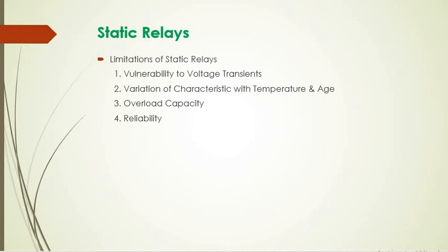Next limitation or disadvantage for static relays is overload capacity. The static relays have lower short-time overload capacity compared with electromagnetic relays. However, with improvement in semiconductor technology, there is significant rise in thermal overload capacity of static relays nowadays. And next one is reliability.